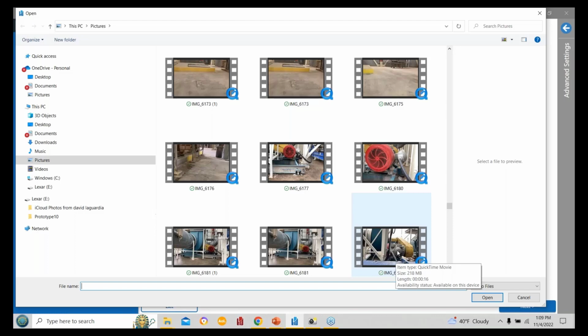When you're doing video ODS, you need to have multiple directions of video taken. It's a two-dimensional software, so you're gonna see X and Y. The straight-on response you're not gonna see, so you're gonna have to have at least two directions to be able to see all the motion that you wanna see.